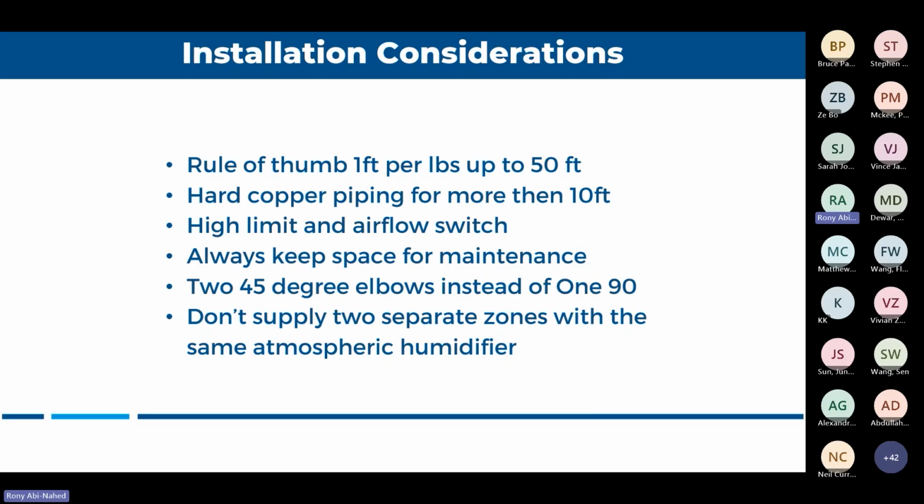I've heard a lot of my competition sometimes saying, yes, it will work. It will not work. We're talking about atmospheric steam here. It can't work because you have steam traveling for 200 feet, condensing all the way. You will end up with nothing at the end of your run. That's physics. More than 65, 70 max will not work. Ideally, stick to 50 feet. If you have pressurized steam coming from your boiler, that's a different story, because you're pushing the steam, helping the steam to go. So yes, you can go to longer runs.